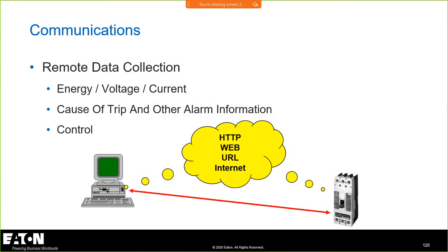The electronics does so much for the ability of the overcurrent devices that it really adds a lot of value from an incident energy reduction, electrical safe work practices, and then the capability to communicate with these remotely. Once you have a brain in there, we can communicate out Modbus, other different types of protocols.